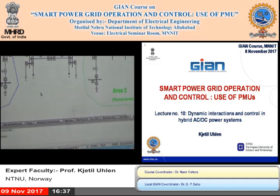4-machine, 2-area system with 2 generators here and 2 generators here. I have sort of modeled these as hydropower units and these as thermal units, but it's not that important. The important thing is that there is higher load here and there, so that there is a power transfer across this corridor between the 2 areas. And we are interested in the oscillatory modes and the behavior of this system.